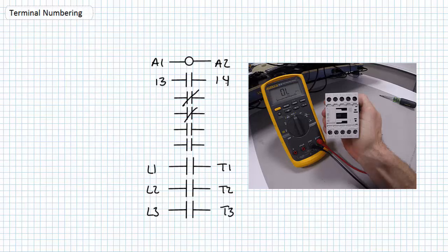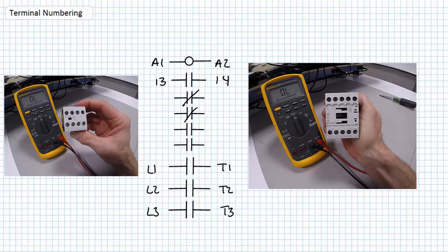coil is energized. If the application necessitates additional functionality, an auxiliary contact block can be utilized that includes other auxiliary pilot level contacts. When the coil is energized by pilot voltage, these auxiliary contacts would also change to their opposite state. Note that the first digit in the terminal numbers for a contactor pilot contacts identify a particular switch, and the second digit pairing indicates that particular switch's deactivated state.